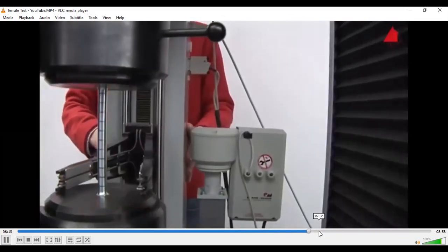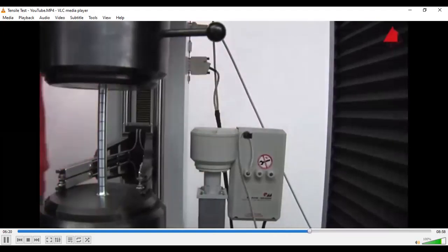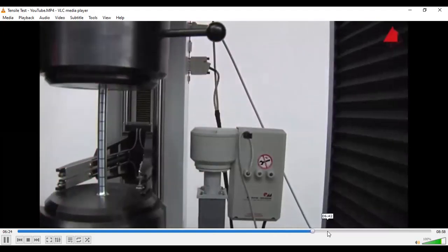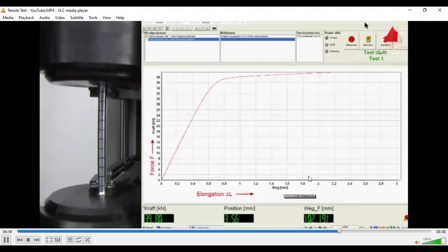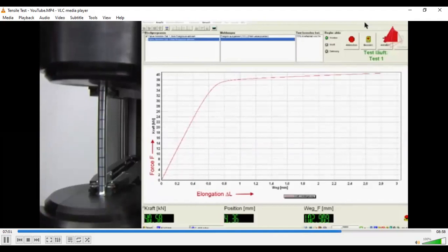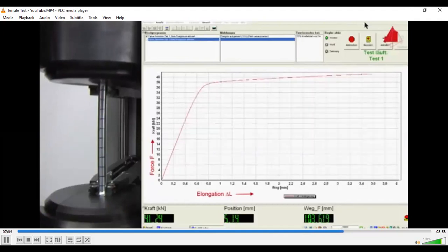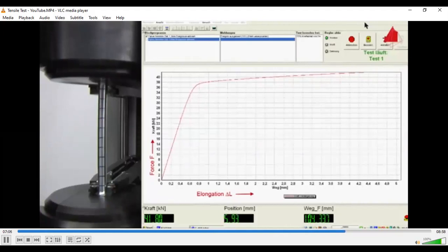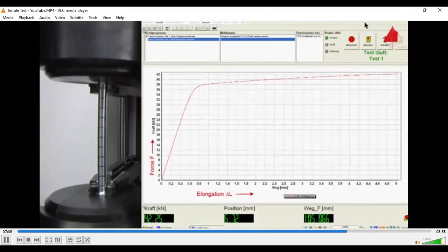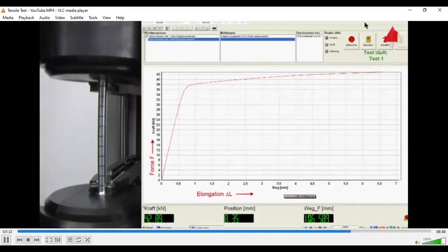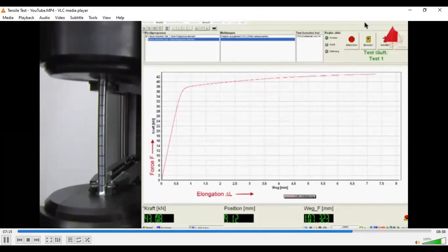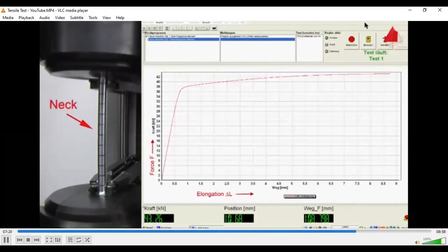After fitting the test piece into the testing machine and putting the extensometer into its working position, the test can start, and it shows the elastic behavior. There is a smooth and gradual transition from linear elastic behavior to plastic deformation. In the further course of the tensile test, the force increases and the test piece again is strained uniformly along its length. At the point of maximum force, a neck develops, and all subsequent plastic deformation is confined to this neck until fracture finally occurs there.